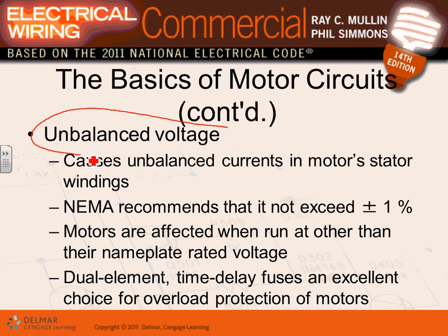Okay, take this. Unbalanced voltage. Now that's a problem. The equipment are rated to run at plus or minus 10% of its rated voltage. If the equipment is rated for 480, you can give it 10% higher or 10% lower, and that equipment should work properly within that range. That's set by NEMA for most equipment. If you increase the voltage higher or decrease the voltage lower, guys, the performance of your equipment will suffer, and I have an example that shows you in a second here.